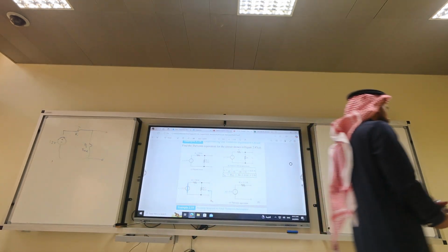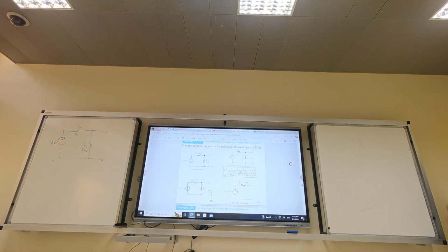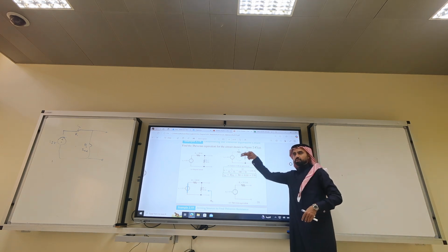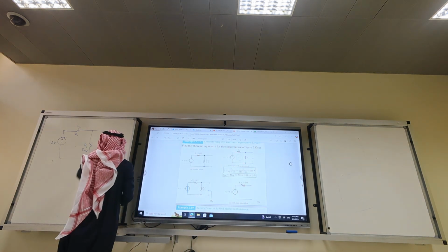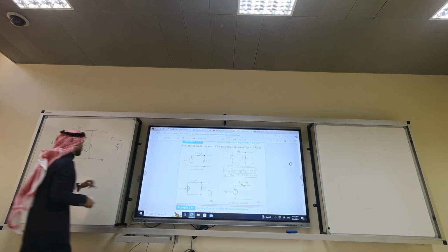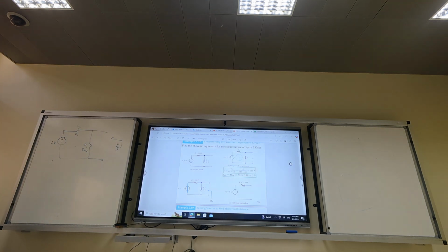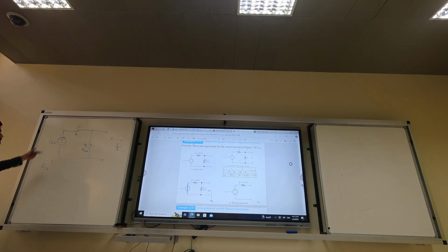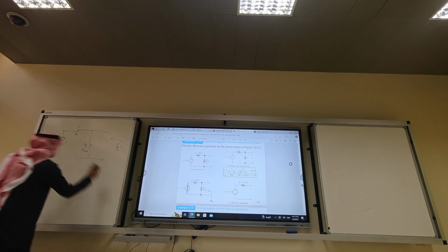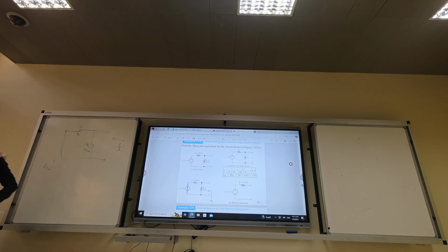In Thevenin and Norton, you're always looking this way. Okay? So where is Thevenin? This is Thevenin, okay? So he's looking that way. So we are asked to find the R Thevenin, okay? What did I say? Every voltage source should be replaced with a short circuit. Get it? Yes. You draw a cable. Now, what is R Thevenin? It's nothing but R1 in parallel with R2.